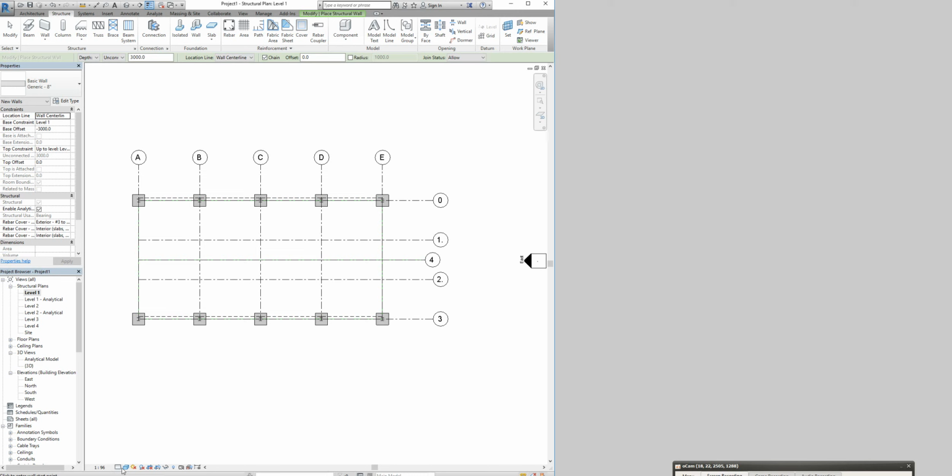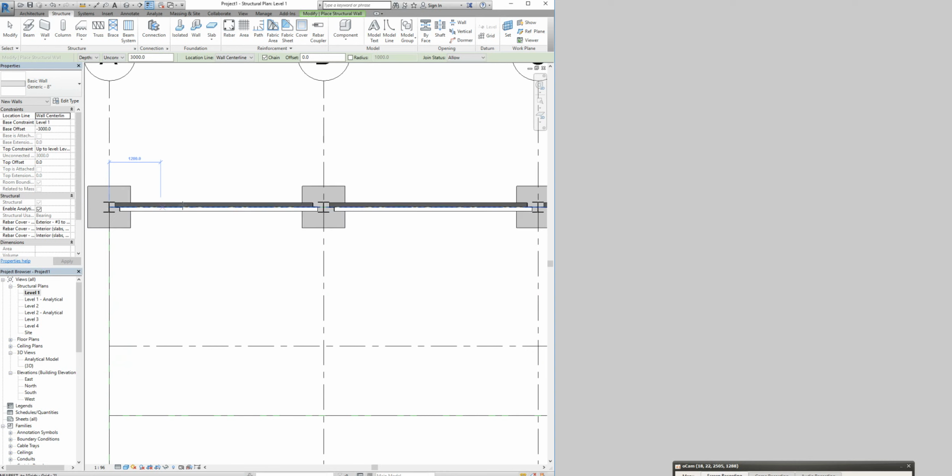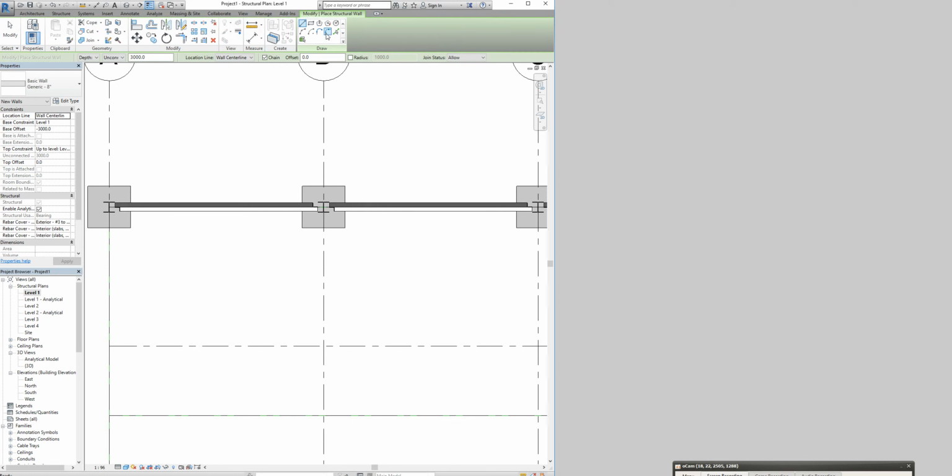So basically, I'm just gonna change my visibility to fine here, so I can see my outer member, which will be the bracing. We are in the wall command here, because we are modifying the wall. We go to pick lines and select the finish face exterior and 235 mil offset. So from here, 235 mil.